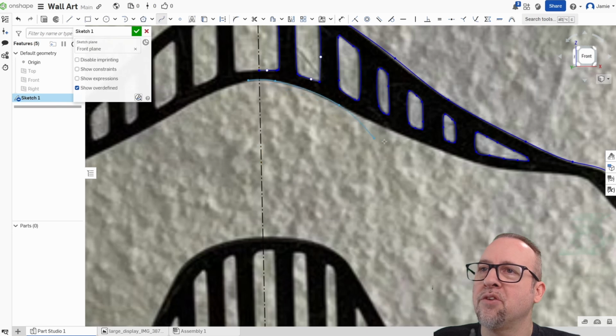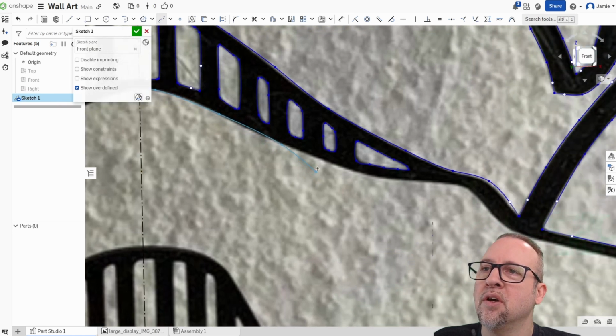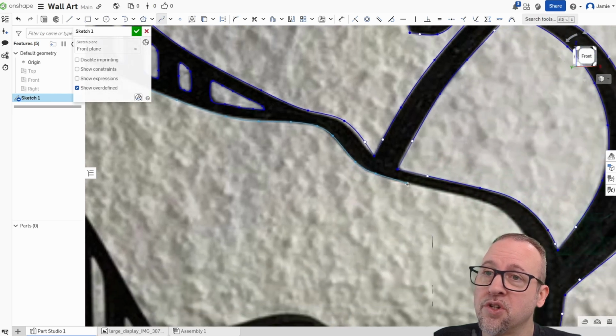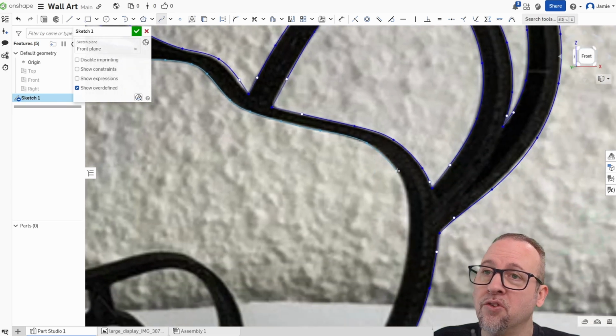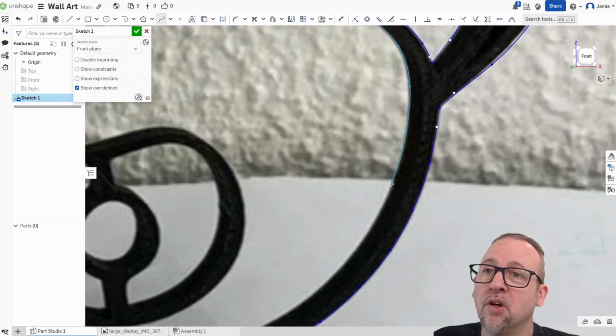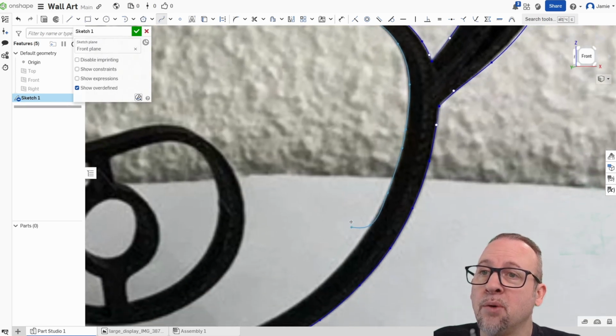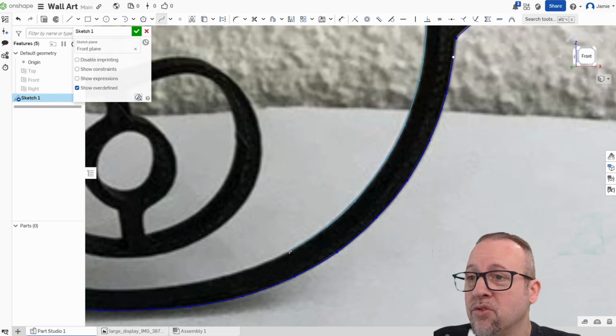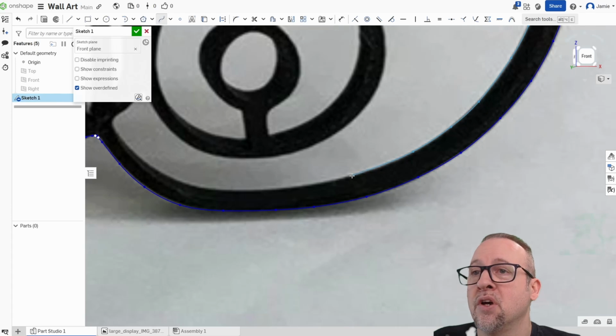We definitely want it past that, because if it's not touching that, then your sketch will not work. Everything has to be touching that line. Very important. If it's not touching, it's not going to let you do the sketch. And this is an unconstrained sketch, by the way, which means it can be modified, and if you move one of these little lines improperly or too much, it might break the whole model, so be careful doing that.